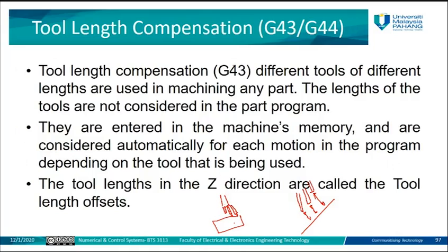This depends on the machine itself, on the tools available in the machine, the length of each tool, and so on. Each company that developed such a CNC machine has its own user guide, which defines all these offsets and all these differences in size and diameters for each machine. So when the engineer does this definition of offsets, they need to consider this for the hardware devices. Then it will be programmed inside the MCU of the machine.